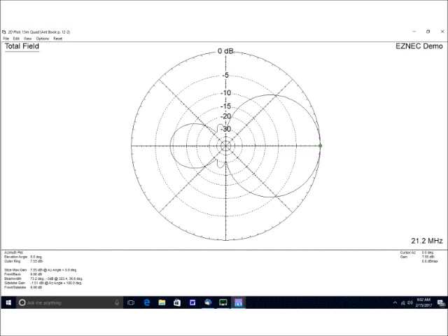Here's another kind of pattern. This is a directivity pattern. This is for a beam antenna. And what we've done here is we've taken most of the energy and we're sending it out in this direction. And what we did is we stole energy from all the rest of it and focused it in this direction. Have you all heard the term antenna gain? There is no gain.